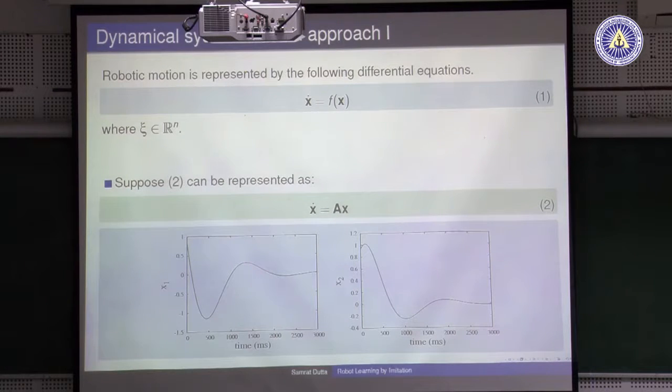First, we have to learn the mapping precisely, so that the exact trajectory is encoded. Next, which is more important, is the stability of the model. Here I have defined that A is negative definite. When we are learning the inverse mapping, we do not have control over the structure of A. So it can be positive definite, it can be undefined.